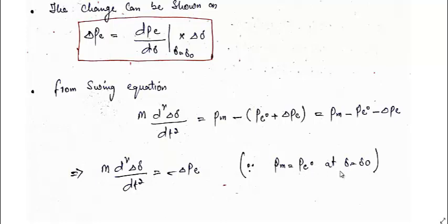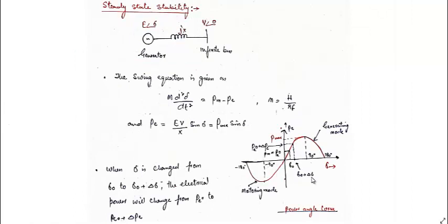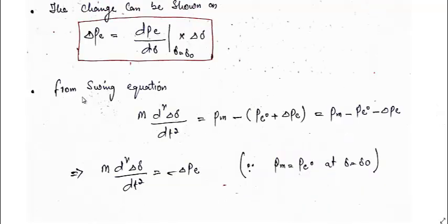One thing you should also keep in mind is that instead of delta I have used Δδ, because I want to find out the value of this change Δδ rather than the actual value of delta. That's why I have slightly changed this swing equation like this.